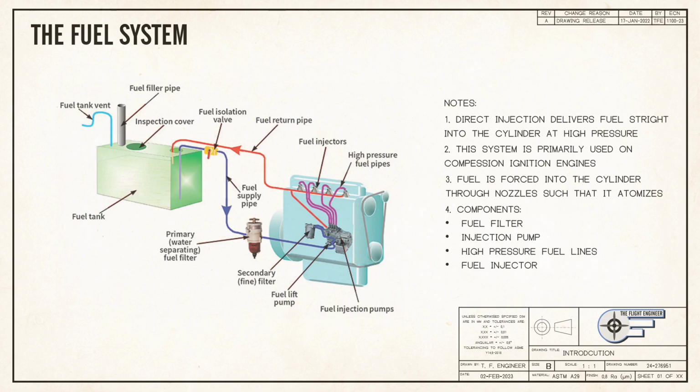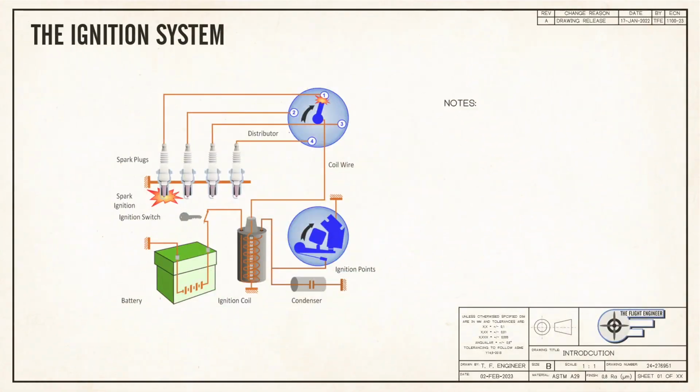Note that this injection pump style of compression ignition fuel injection is just the simplest form of the system. Cam-driven and electronically controlled systems are common today, and modern fuel injectors are incredibly complex components that really deserve a discussion of their own. Moving back to spark ignition engines, we'll look at the ignition system itself.